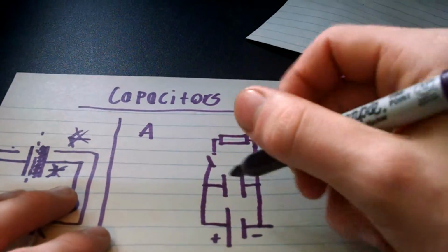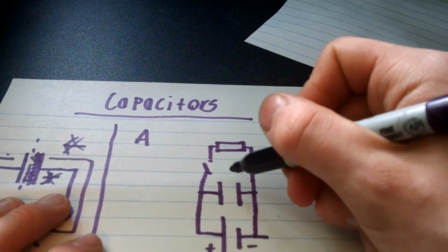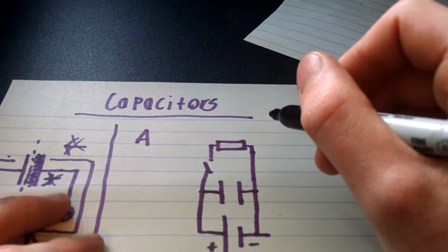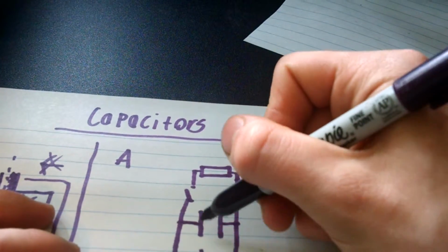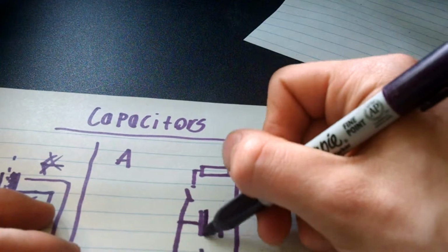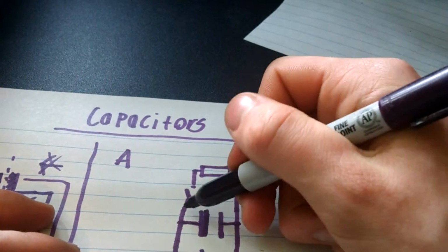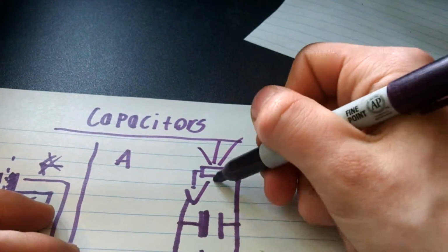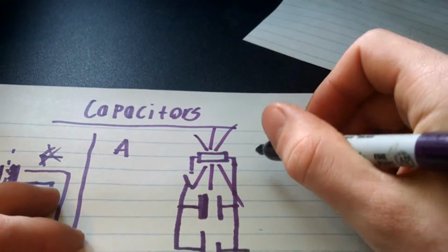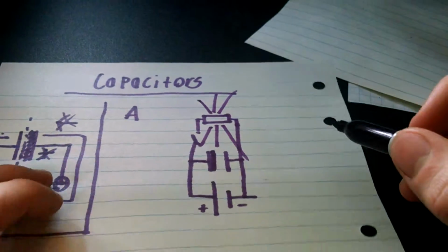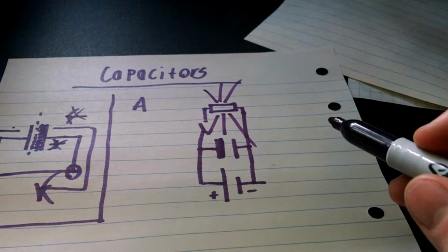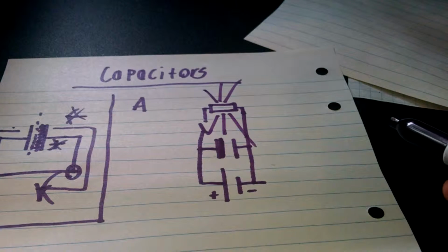Okay, so we have a battery that charges up the capacitor here to around 200 or 300, 400 volts, around that range. Medium voltage, I'd call it. So all these electrons are stored up in this side of the dielectric. Now it's only when we complete the circuit that they all discharge into the flash tube at the same time. Because the flash tube is filled with an ionizing gas, it releases a very bright flash. Now this is utilizing their discharge property.